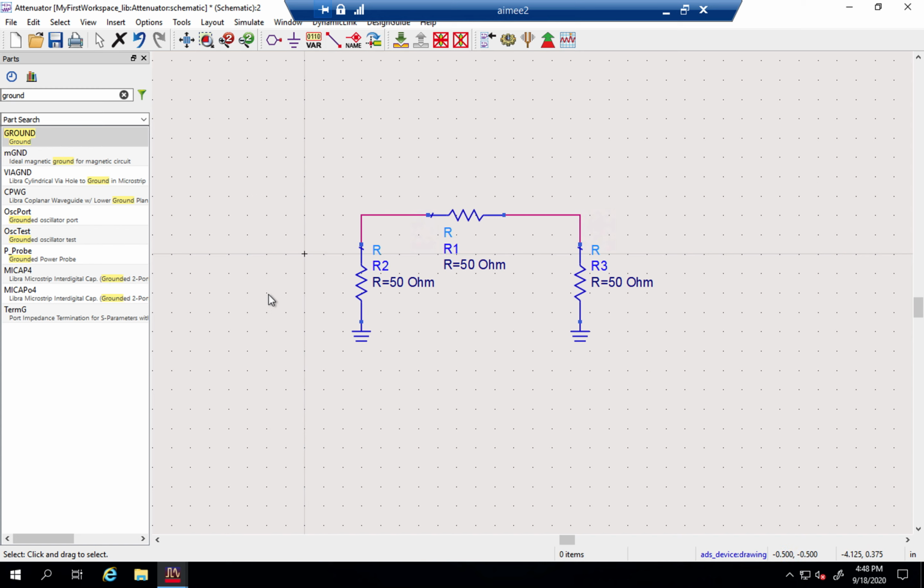All right, and that's the basic circuit. This is the equivalent of putting in the model in ADS. Next thing is you have to define or create a solution or a simulation that you want to run. For this one, we want to run an S parameter solution. You may or may not be familiar with S parameters, but usually they characterize a 2, 3, 4 port network. This one here is just a 2-port network. We send in power or voltage here, and we monitor the output.